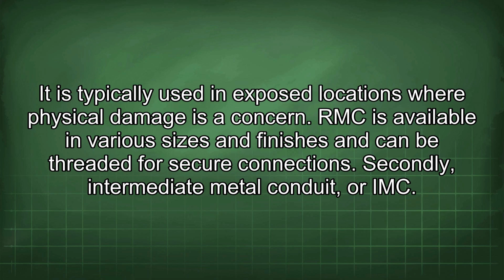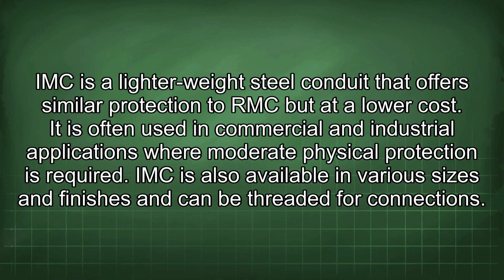Secondly, intermediate metal conduit, or IMC. IMC is a lighter-weight steel conduit that offers similar protection to RMC but at a lower cost. It is often used in commercial and industrial applications where moderate physical protection is required. IMC is also available in various sizes and finishes and can be threaded for connections.